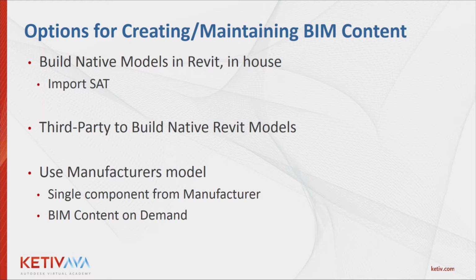This is new to 2017 R2 for Inventor, which allows you the capability to build this BIM model and then use Configurator 360 to be able to supply that to an architect or someone wanting to use your model. They choose which configuration they need, and they can get what we call an RFA model, a Revit family model for Revit. So those are the three different ways that we look at supplying this content.